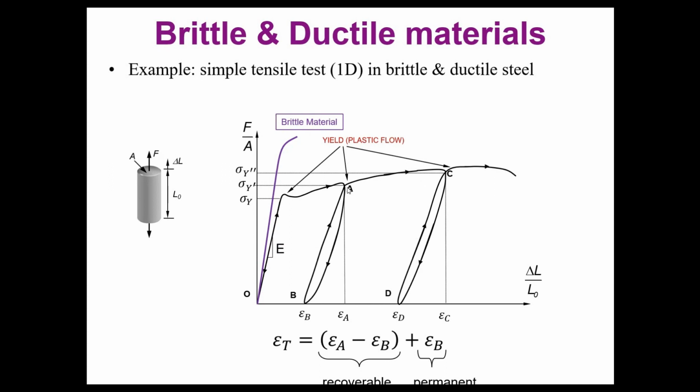So what we notice is that it's not only that there is a change in the behavior and we start having plastic deformation, because here you see that when you unload, you recover only part of the deformation and you keep certain plastic deformation that will be there forever, even without loads. It's not only that, but the strength that started at this value sigma y is going to increase to sigma y prime and to sigma y double prime if you continue loading, unloading and reloading.